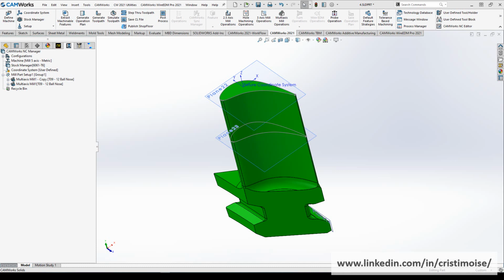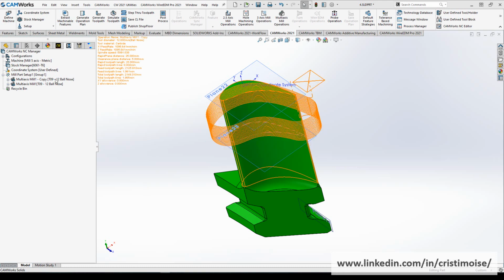In the gauge checking tab, we have a new option for minimizing tilting when the strategy is set to tilt tool and the angle definition is set to automatic. In sort machining, multiple cuts have a spiral sorting option available. And in entry and retract tool axis orientation, you now have the option to set it to automatic in order for CAMWorks to calculate the best toolpath.